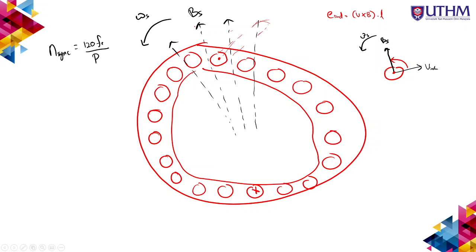Okay, so now there is current. So now the current is induced. So once there is induced current, what happens? So we have learned this in chapter 1. Okay, so in chapter 1 we also studied the production of the induced force on a wire. Okay, so there is a force equal to, we do it like this, the cross product, I with B times L, right?